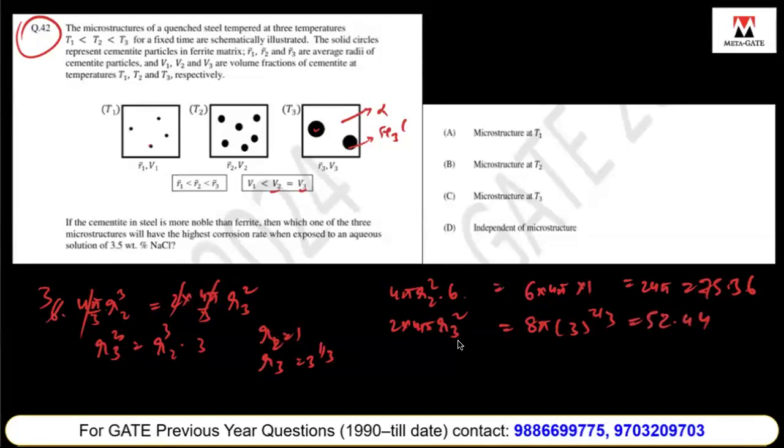If you'll see in the third case, anyhow, the cementite acts as cathode here. Fe3C is cathode and anode is alpha. So alpha should be as high as possible, because whenever the first material which corrodes is the anode itself. So anode should be as large as possible; there should not be a significant area relation between anode and cathode, it should be a very large difference.